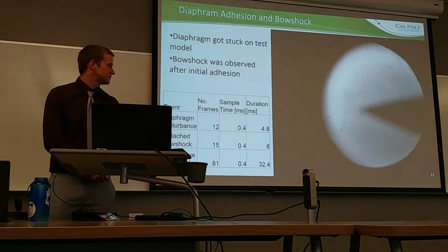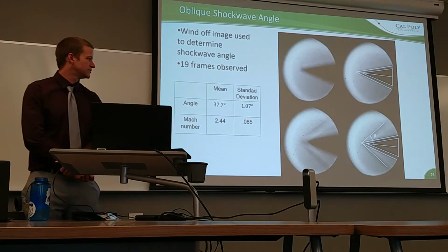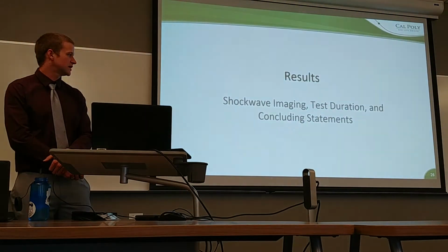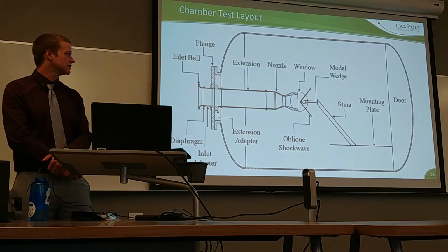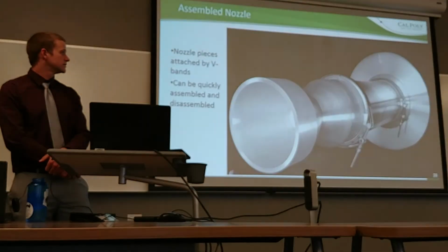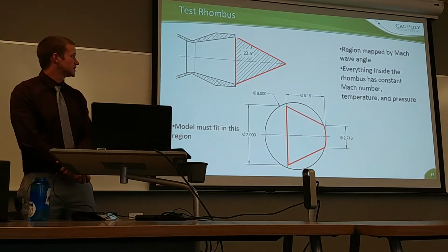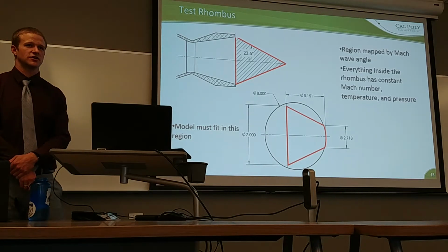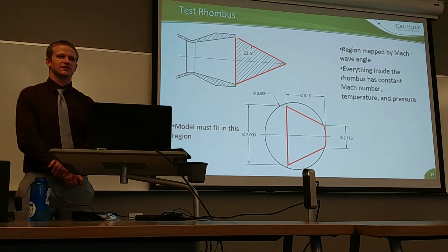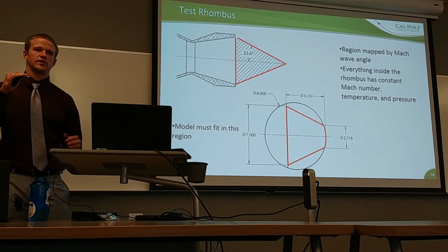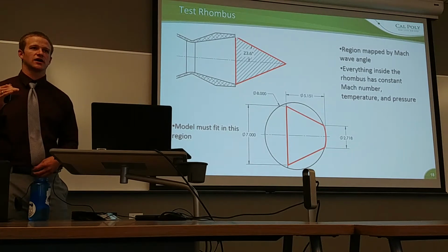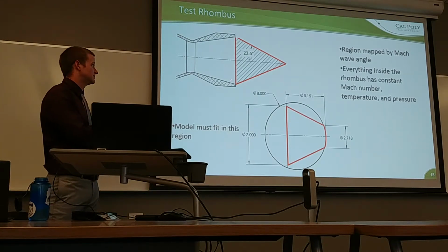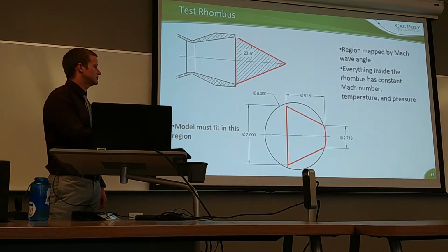So the question was whether what's on the side of the test rhombus are shock waves. It's actually slightly different. It's called a Mach wave. So it's not technically a shock wave. What it basically is, is the line that the weakest possible conceptual shock traces through the flow.